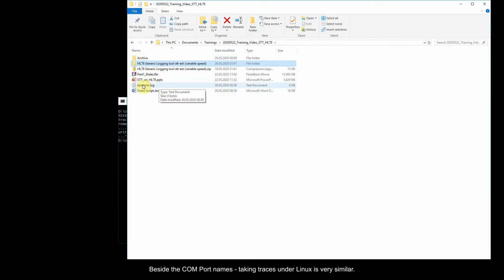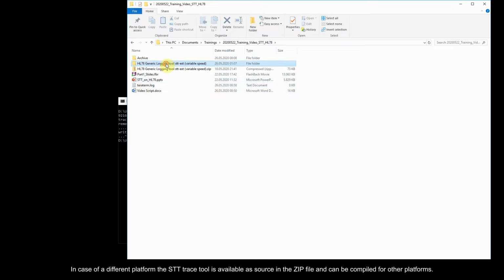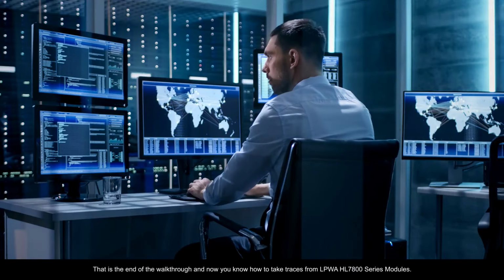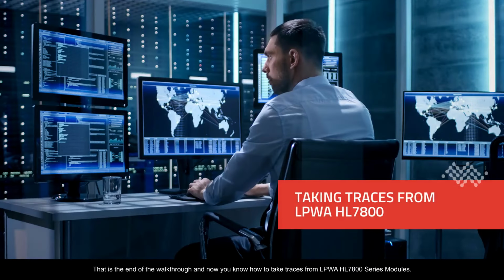Besides the COM port names, taking traces under Linux is very similar. In case of a different platform, the STT trace tool is available as source in the zip file and can be compiled for other platforms. Check the README full ext.txt for compilation advice. That is the end of the walkthrough, and now you know how to take traces from LPWA HL7800 series modules.